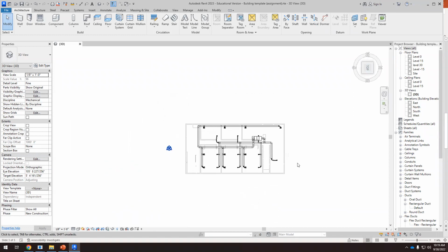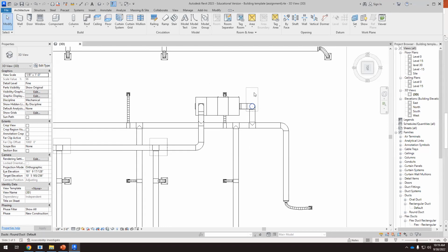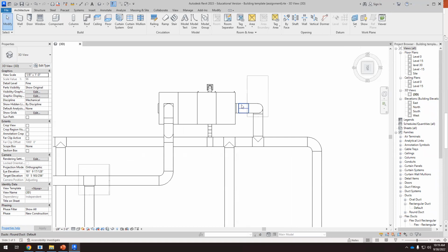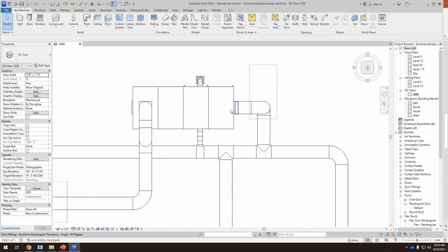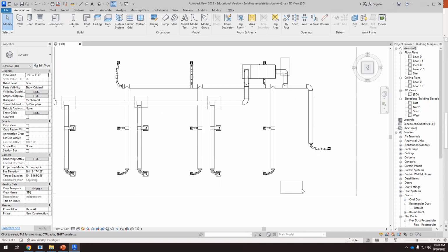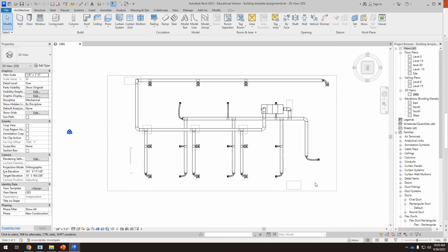Okay, so if we analyze this building, you see that we have different shafts here. We have shafts here in the classrooms. We have a shaft here where the supply duct is close to the air handling unit. Well, we placed the air handling unit close to this shaft to minimize the supply duct here. It goes immediately into the building. And we have another shaft here, and probably this shaft is the right one for the exhaust pipe that comes from the boiler.